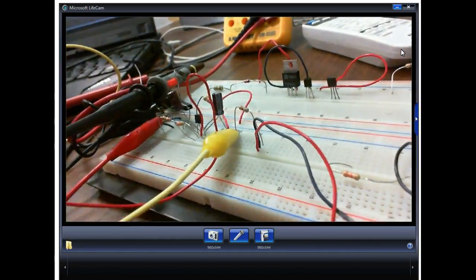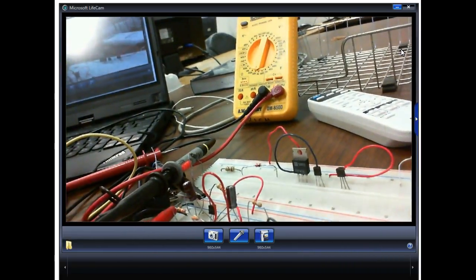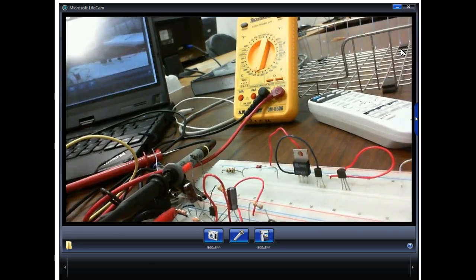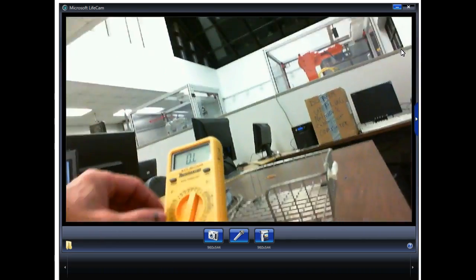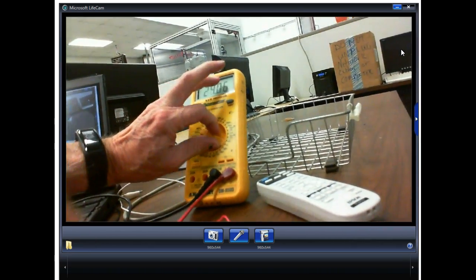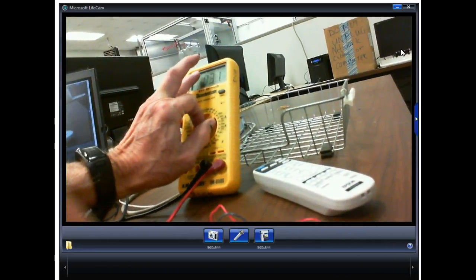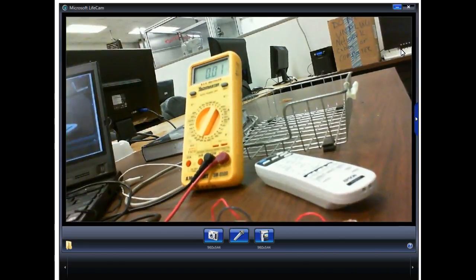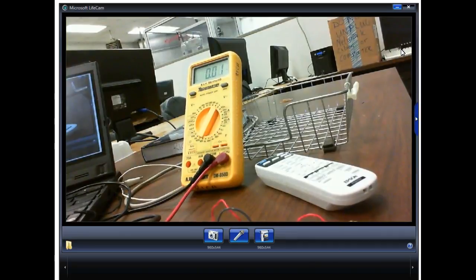So we're going to come up here and open it. Make sure we still got VCC. Okay. So I've opened R1. I'll turn the power supply back on. Put my meter back on volts. And what's the first thing we need to measure? Okay, VB. So here's VB.